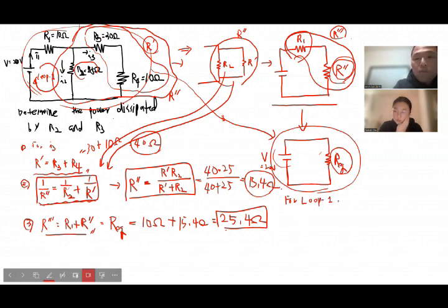As I said, do you remember that basic junction rule and loop rule I showed you last session? If the battery is aligned in the same direction as your loop, then the battery always raises the potential and brings it up. And if your current path and the direction of the loop are the same, then the resistor always knocks it down. So it comes with a negative sign. Okay, that's just a rule of thumb.